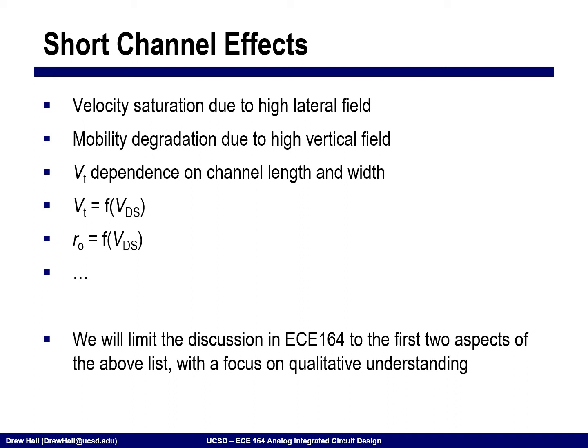And so the mobility of the silicon goes down. The VT dependence on the channel length and the channel width. This is effects like DIBL, drain-induced barrier lowering, coming into play here. We also know that VT is a function of VDS, r0 is a function of VDS, and on and on. So there are many short channel effects that are causing all of this.